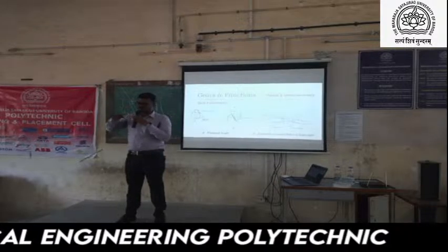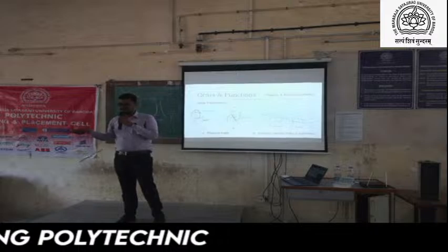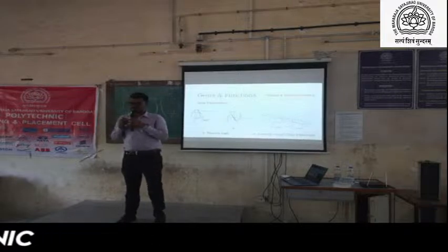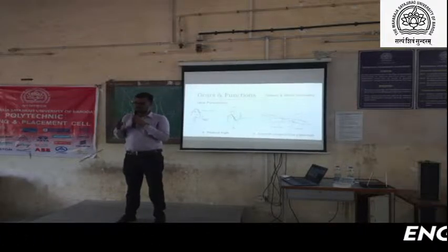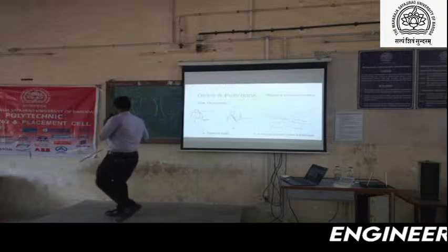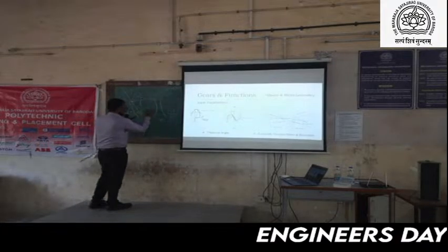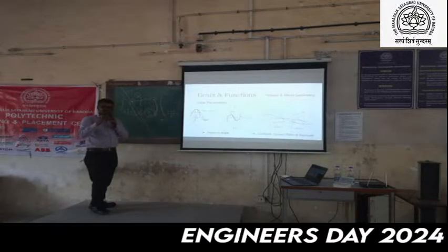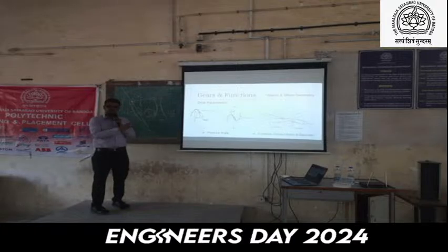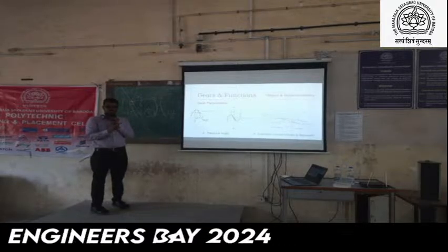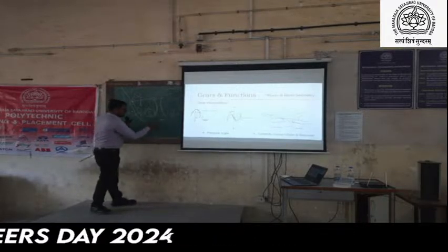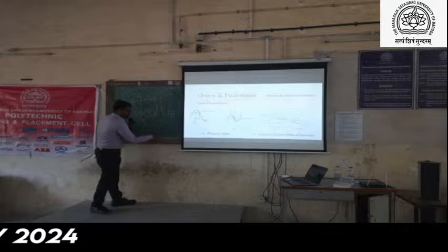Compare that with helical gears. The contact ratio will be a little bit higher. Generally, in a round figure, 3 teeth will be in contact for helical gears, but 1 is in full contact and 2 are in partial contact.